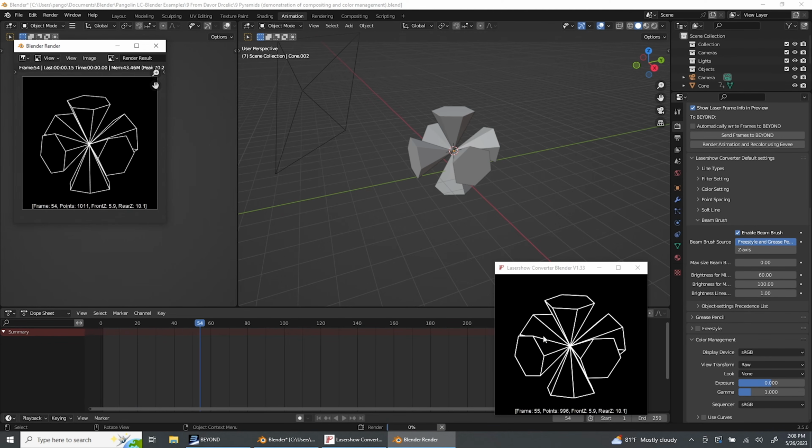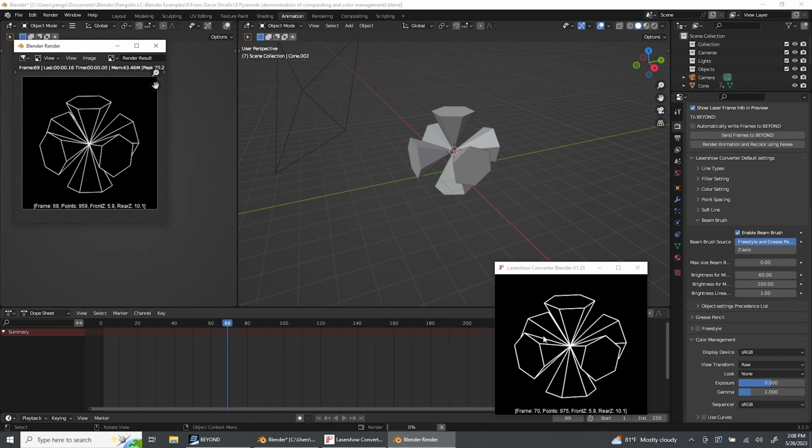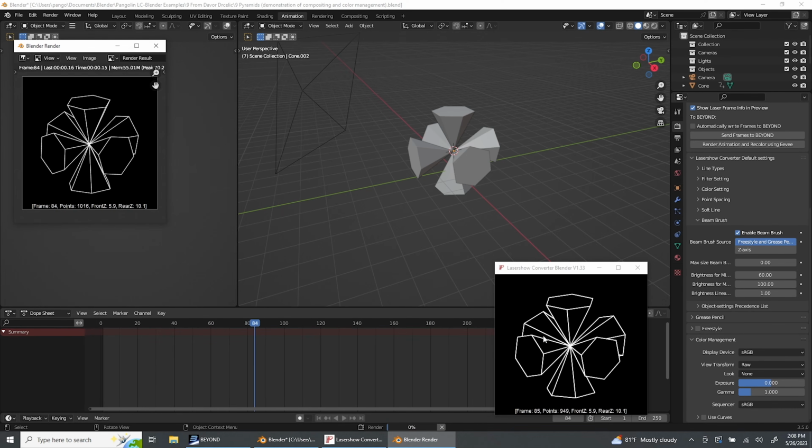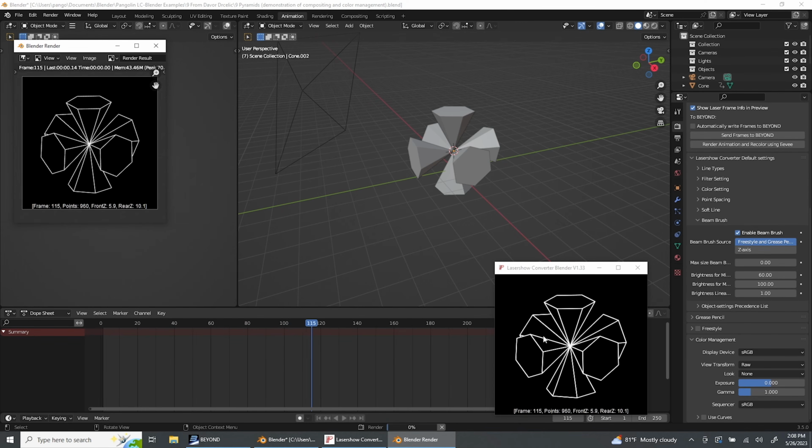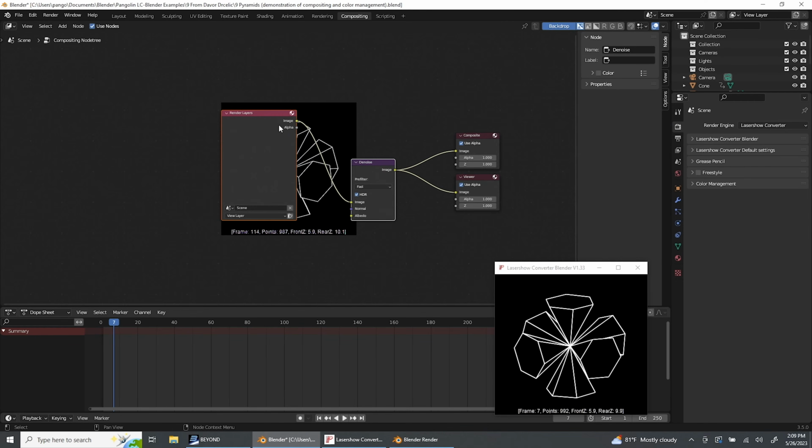So I'm wondering why it is that our renderer is taking so much time with this. What's happening with our renderer? Our renderer is blindingly fast. It shouldn't be taking this much time to do just such a simple scene. And so when we looked into this, this is what we found. Up here in compositing, Davor is a professional Blender user, and this is something that he does a whole lot, is uses this compositing stuff. And compositing happens after the whole rendering operation. And so he's got this denoising thing, and this takes time. In fact, it will take even more time the bigger that window is.